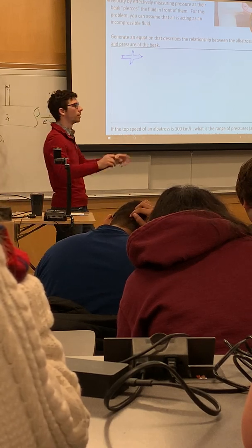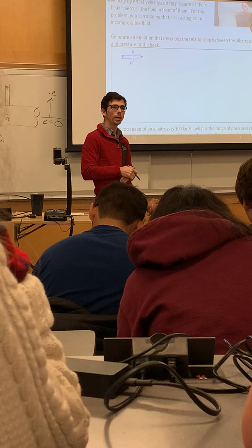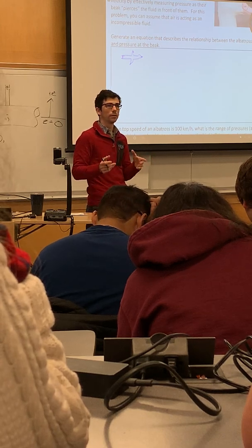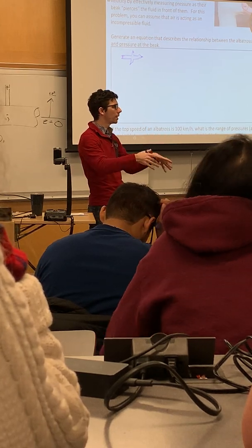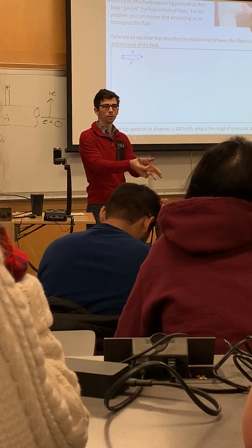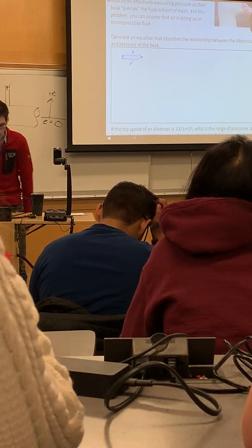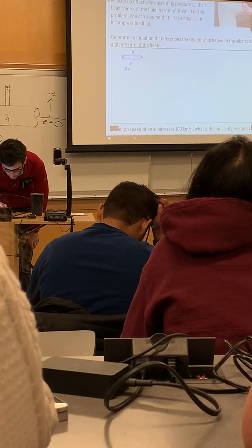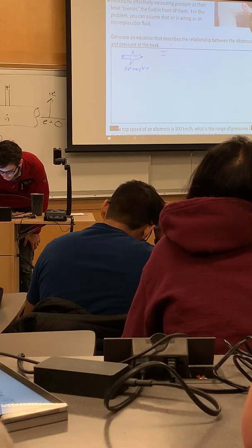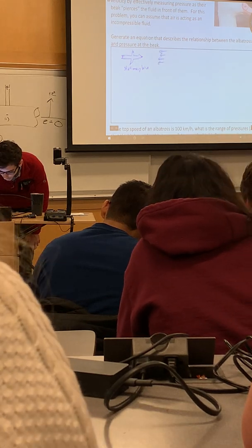You either drive the vehicle and see how it behaves aerodynamically. That would be expensive and difficult to control. Or you could put the vehicle in a wind tunnel and move the fluid and take the vehicle to be stationary, right? So let's take that assumption here. We've got a stationary bird, but we have the fluid moving at some velocity.